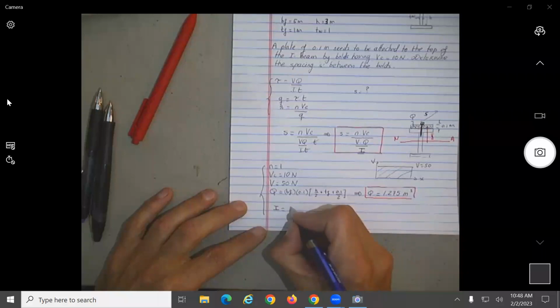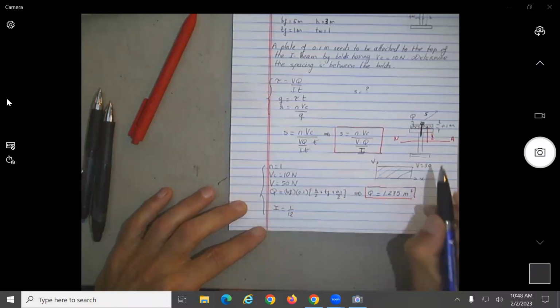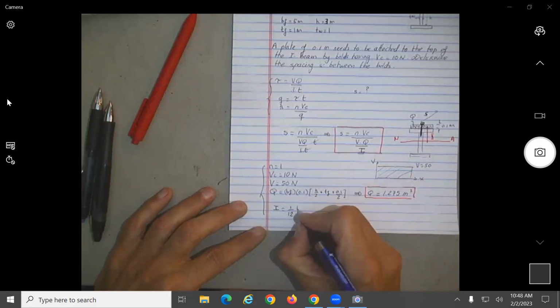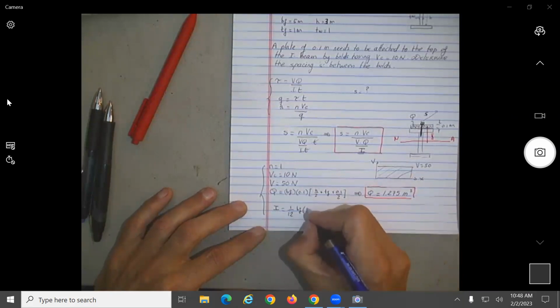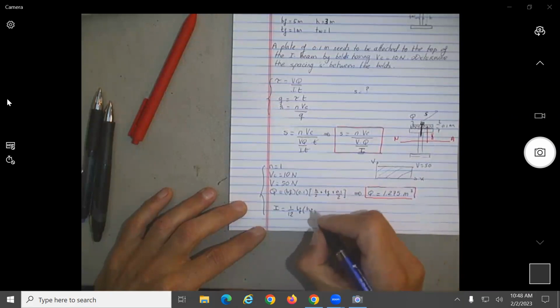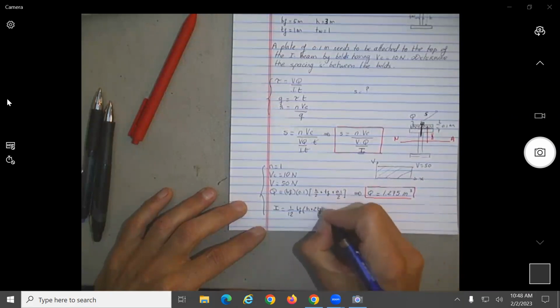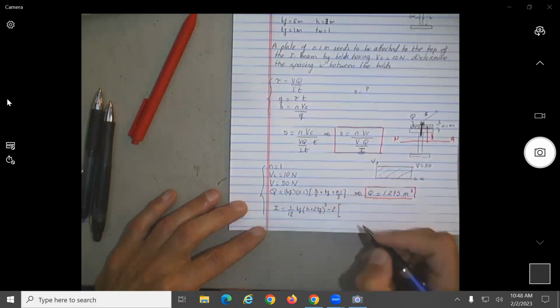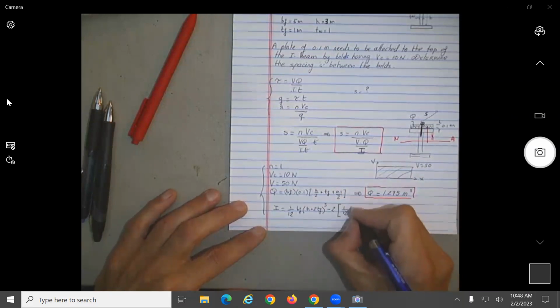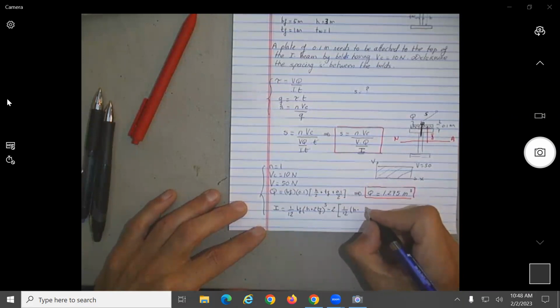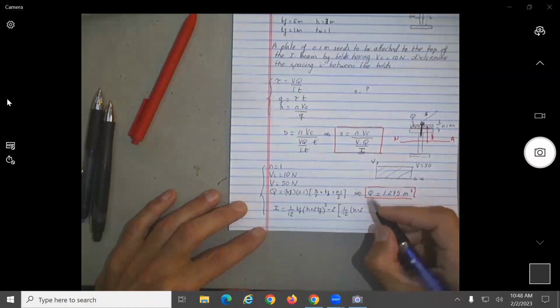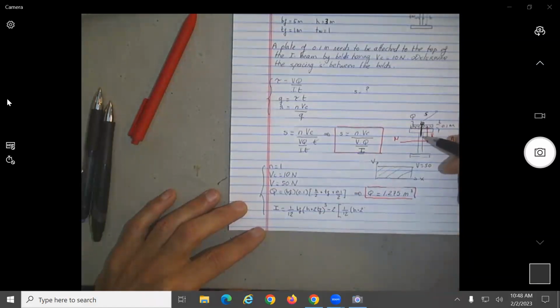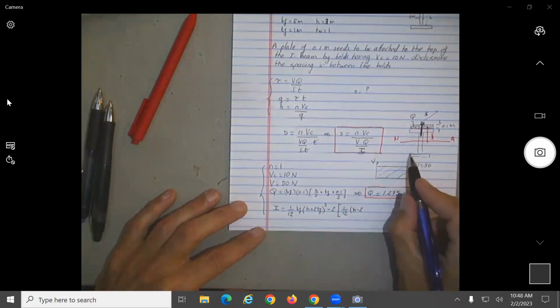So let's do as before. So this will be equal to what? 1/12 over, we do as before. So BF times H plus 2 times TF cube. This time I'm going to do it right, minus 2 times 1/12 of H minus T of H, no? H should, yeah, the base, sorry, the base. I want to look at the base first.